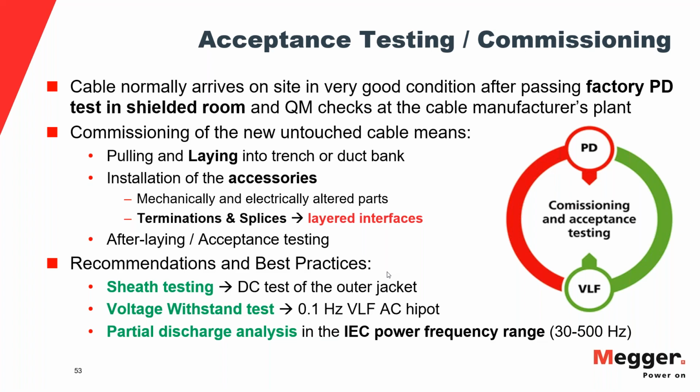If you have 3 phases and maybe just one of the 3 phases is soaked with water, or one joint, the tan delta might be different there, but then you still have to find out where it is. So it's, again, not a localization test, but it might indicate a very specific problem with water in the cable. Now, on a new cable, unless you left it open overnight and it rained and whatnot, there is no aging condition in there, and nothing you can measure in relation to water. So, plus, again, the effect of copolymer cable additives and whatnot. So you're not measuring anything useful there.